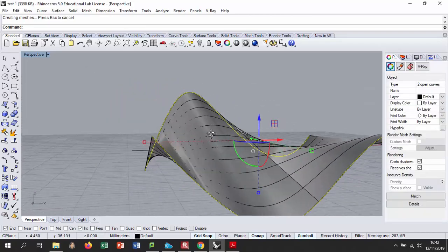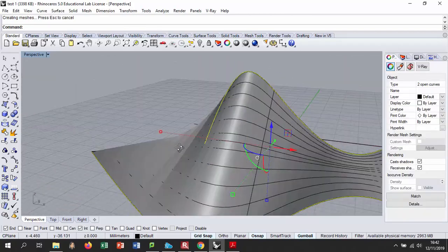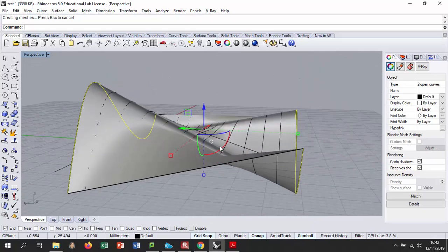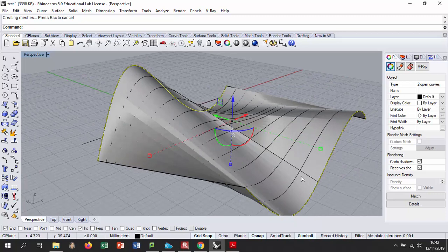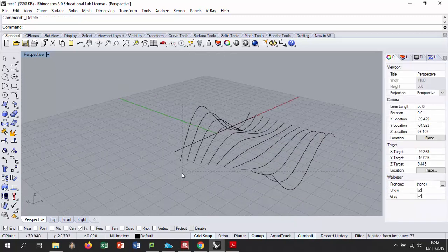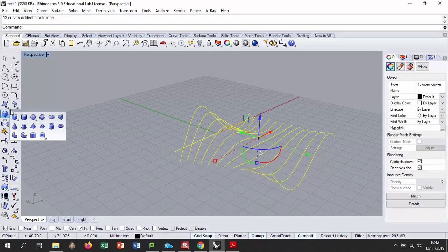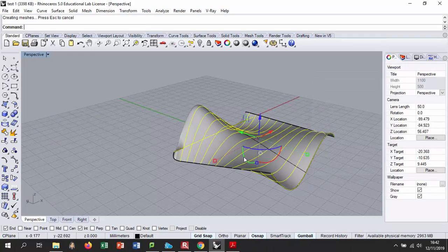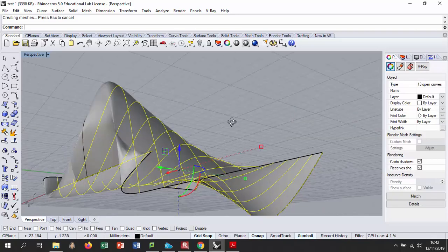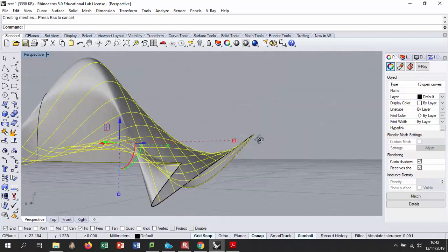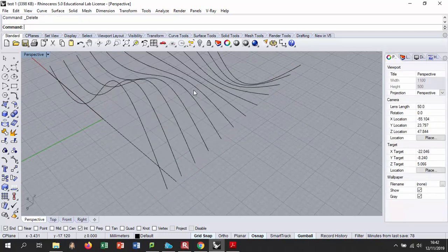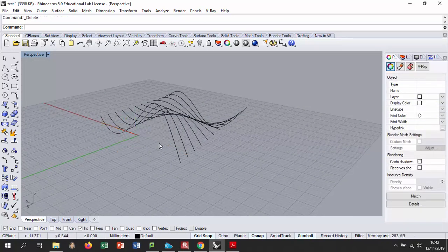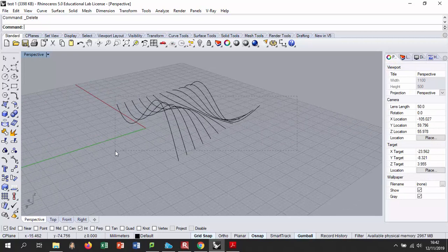As you can see here, it creates this chunky transition where you don't have that smoothness that you might want. So if you delete that and select all of these and go to loft, you can immediately notice, well, one of my curves is, I did not, yeah, because I selected also the reference curve, delete that.